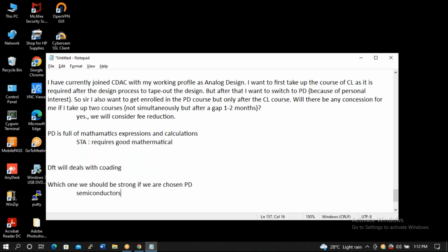Let's say there is a CMOS latch. When you study CMOS, you will come across a topic called CMOS latch. It's a problem. How to solve that problem during the physical design flow? Let's say there is something called drain induced barrier lowering, DIBL. How do you solve that problem? Hot electron effect. How do you solve that problem? You require that kind of fundamentals.